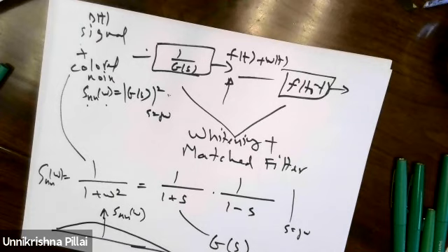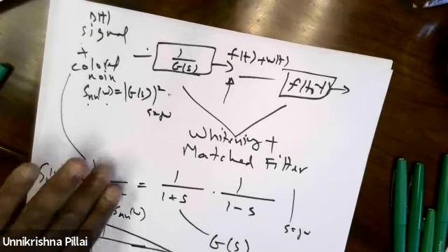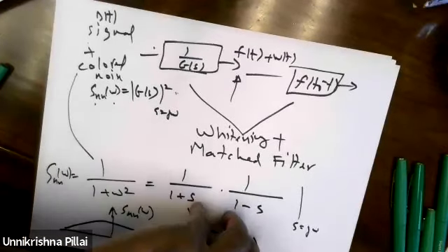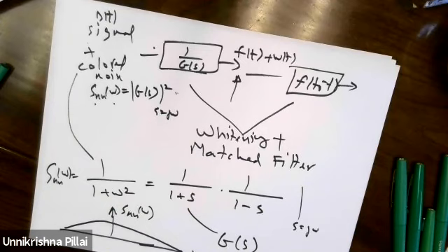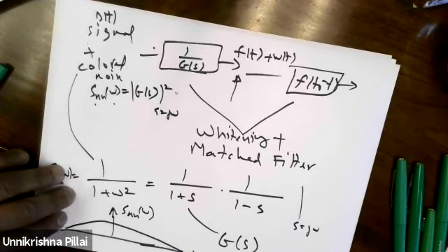Let me tell you the hard way. You observe a lot of data. From the data you observe, estimate a lot of autocorrelations. Remember last week we went through ergodicity and how to estimate the autocorrelations. Once you estimate a large number of autocorrelations, you can compute the spectrum. But then you have to make sure that the spectrum is non-negative. Once you get the spectrum, you can do a factorization and get this filter. Then you flip it, you will get the whitening filter. Is that clear? Yes, thank you. Yeah, so you have to do some work.